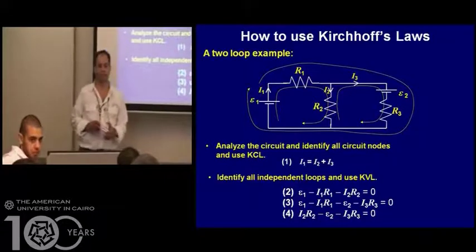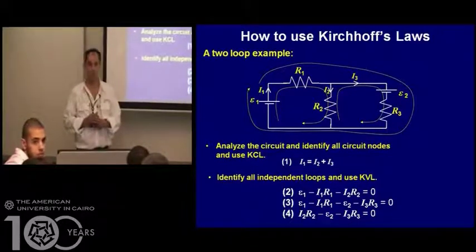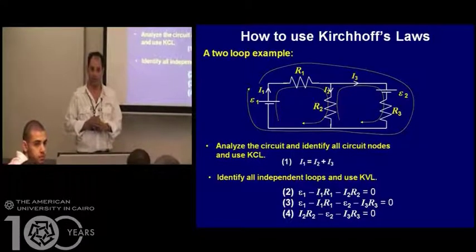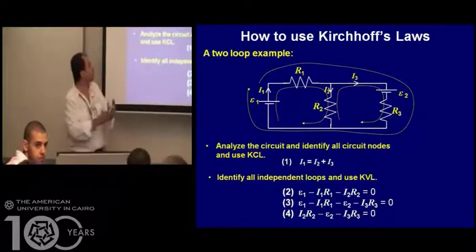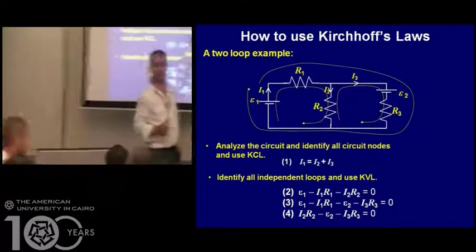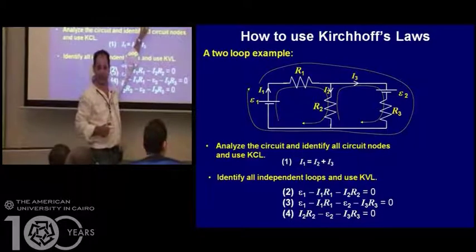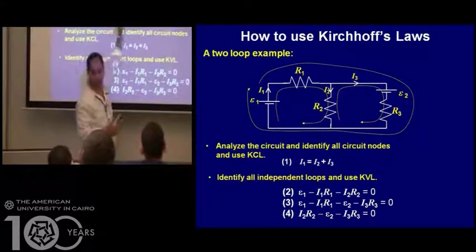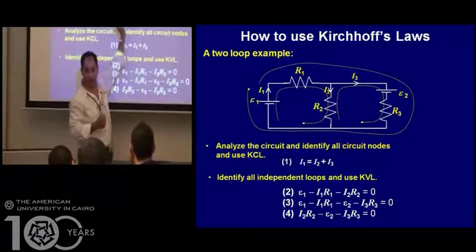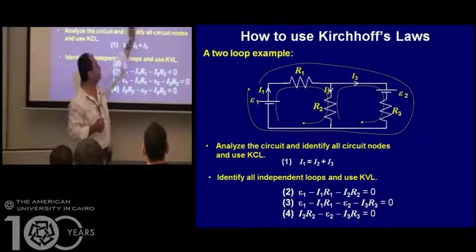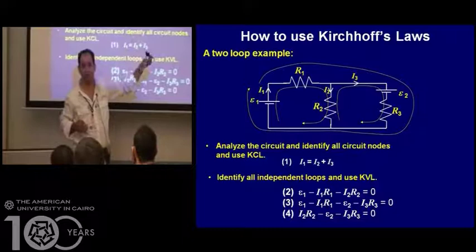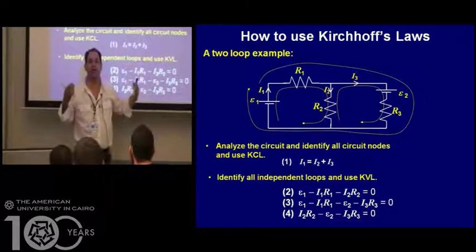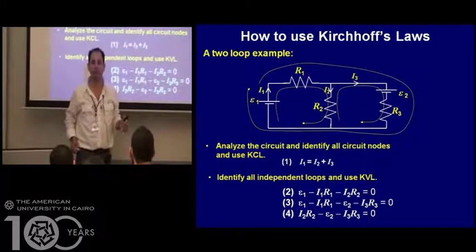There could be two currents going in opposite direction in the same branch at the same time. Yes, and the net of them, I call it I2. The resultant of that, I call it I2, and I call it I3, and I call it I1. So again, I1, I3, I2, those are not the currents coming out from the batteries. Those are the net current in those branches.